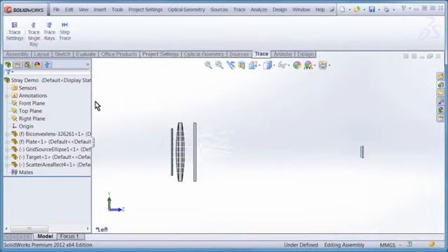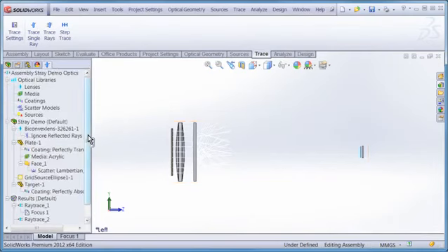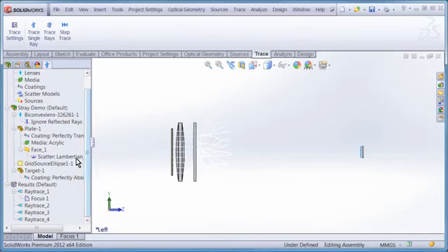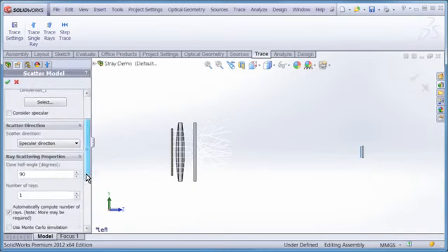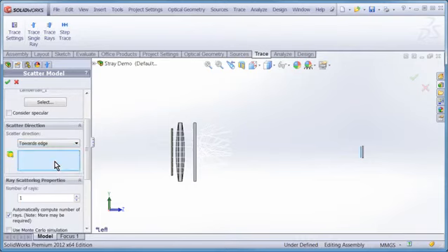The other thing we need to do after changing the project settings is we actually have to modify our definition of our scatterer. So let me come over into my Optics Manager, and I'm going to select the scatter face right here, right-click and then Edit. Instead of scattering light into the full hemisphere relative to the specular light, what we're going to do is scatter towards our defined importance edge.